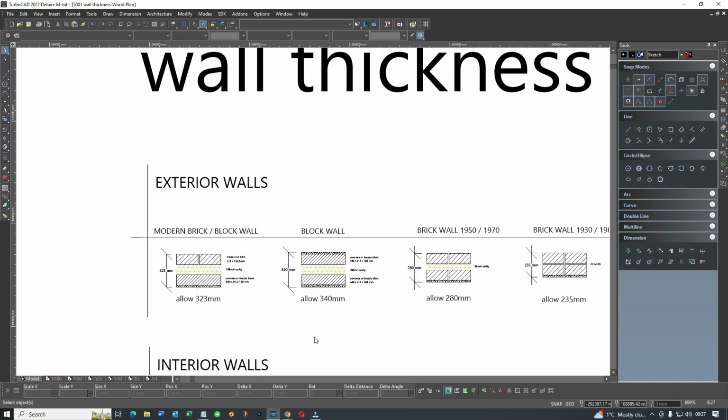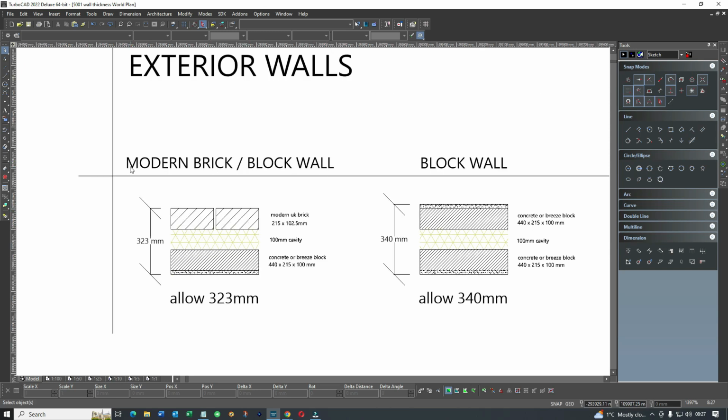And obviously if you're a seasoned veteran and you know this, then that's fine, but this is for the UK property market, so the sizes are all metric. We're going to start today with a new build house, or adding on an extension to a house today. What we're looking at is a brick facing extension. You're looking at a modern brick. A modern brick is metric, and it's 215 by 102.5. These are the numbers you need to be concerned with.